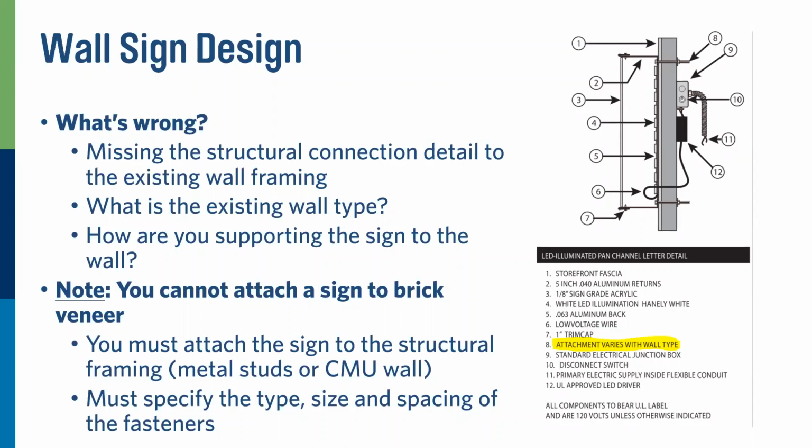You know, wind load. But what's happening is because all these signs project out from the building, like a hammer, they have a leverage on it. So the bigger the sign and the smaller the raceway, the bigger the leverage arm on it. So you're always better to put your anchors, your bolts, further apart.